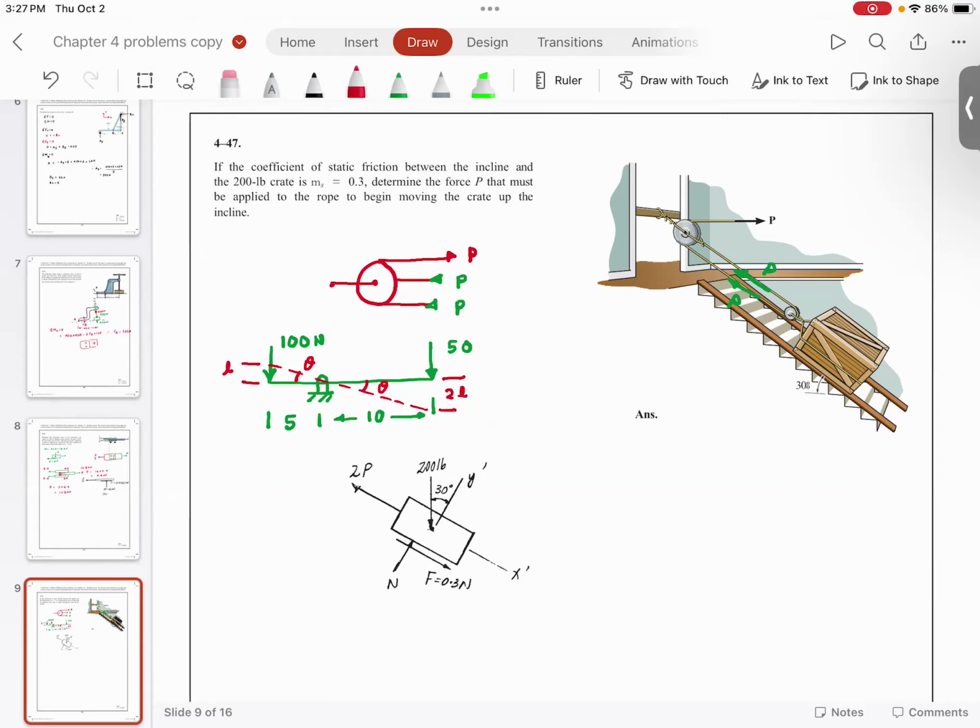So that's why if you have to climb a hill, the vehicle needs to go up, you downshift because you need more torque. So energy remains the same, but torque and speed change. Similarly, the force and displacement relationship changes, but at the end of the day, you get a mechanical advantage.